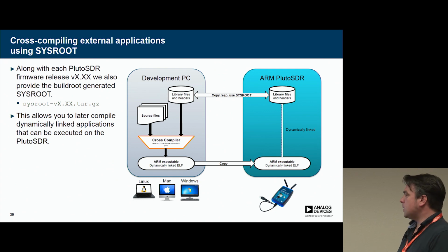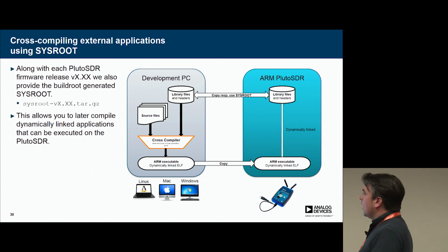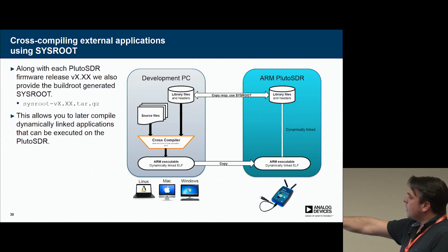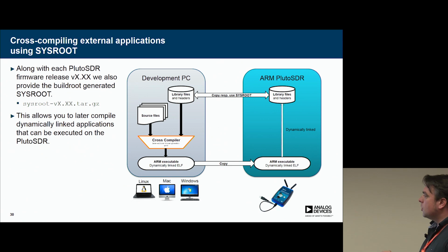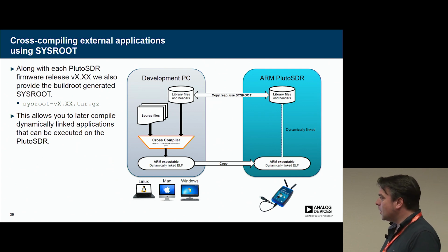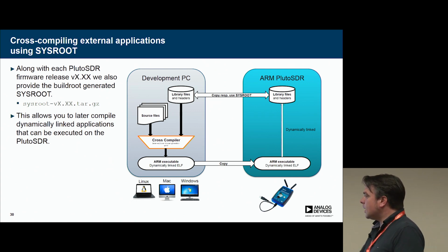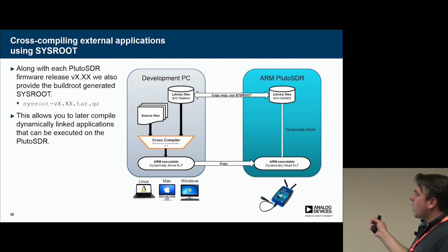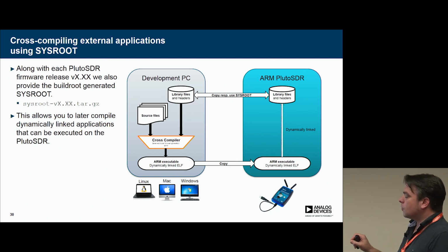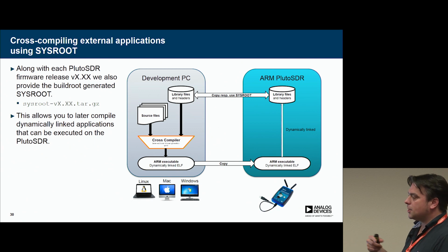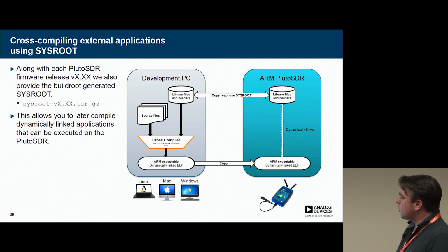The sysroot is basically the library files that are deployed to the Pluto, that are in the PlutoSDR firmware root file system, and which applications link against. We provide a copy of them for your development PC, so you can link applications against those libraries and then copy them over to the target.